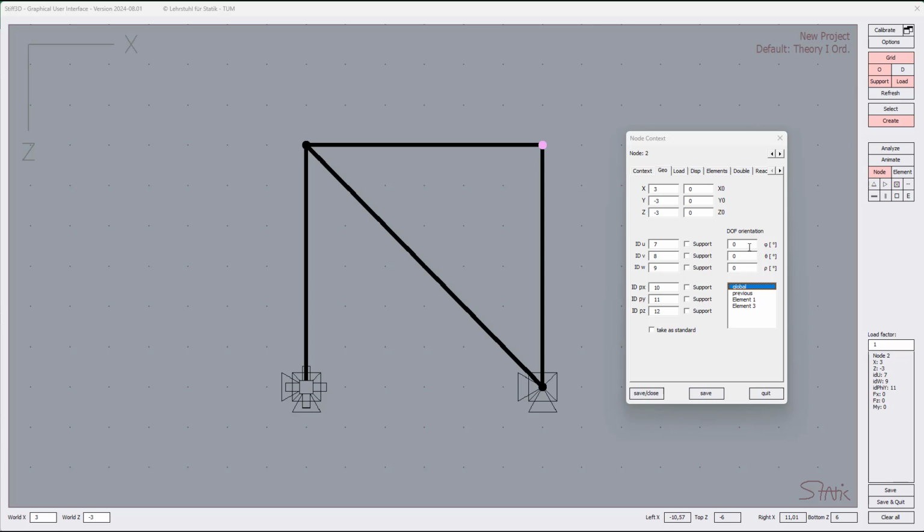And if we now apply a load, perhaps I give another example here, choosing phi equal to 3, and we now come to the point, what is the load fx? Now you see the load is aligned to this local orientation. Also, we have now the possibility, even if there is a local coordinate system defined, to give in the load globally instead of locally. Then you see that the load is just oriented along the global system, top left, rather than to the definition of the local coordinate system at that node.